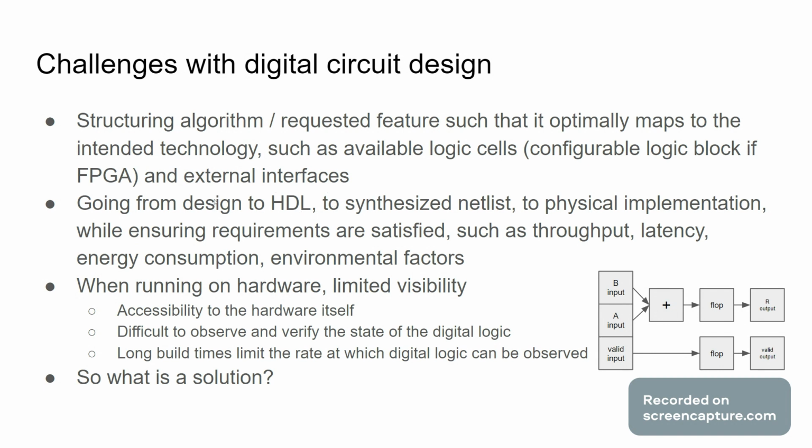And while you're doing all of that, you might have to worry about external interfaces. There might be a processor that you're trying to speak to, or there might be a DDR interface that you're trying to write to. There might be some MGTs, multi-gigabit transceivers. There's a lot of considerations when building an FPGA design.